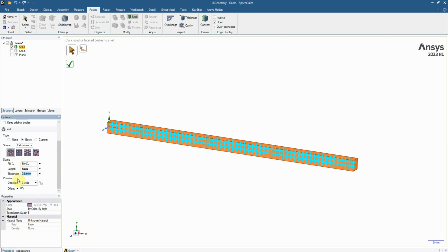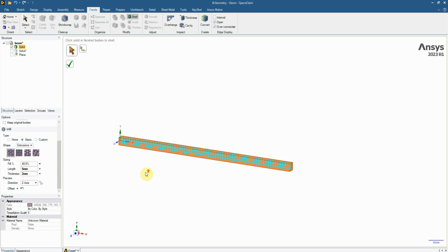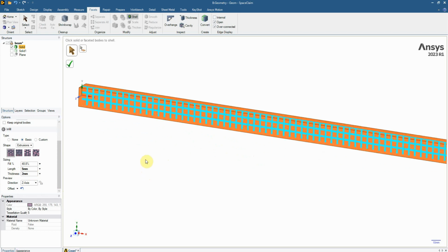But then here you've also got the thickness of each of these. Now if the outside is 2 millimeters, keeping this one 2 millimeters keeps it nice and confined. So everything is 2 millimeters. So thickness is 2 mil. The inside or the outside shell thickness is also 2 mil, and you can now start playing around with the length. So, you know, having 2 millimeters will create something like this,